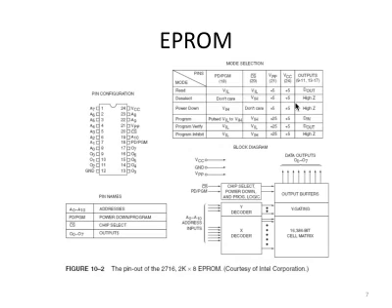Now if you do simple math, 2 to the power of x equals 2K. What is x? It's going to be 11. That is to say, you're going to have 11 pins used as address for this chip. That's how you can select 2K locations.